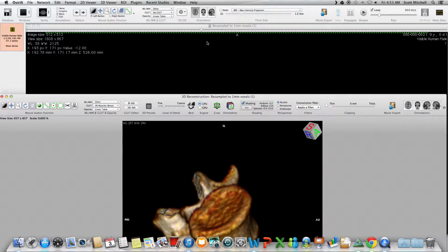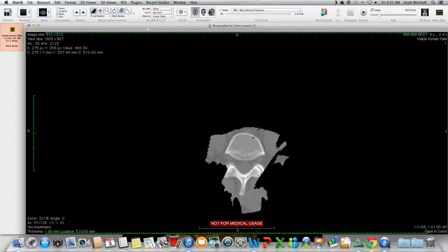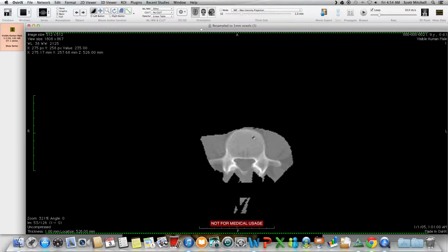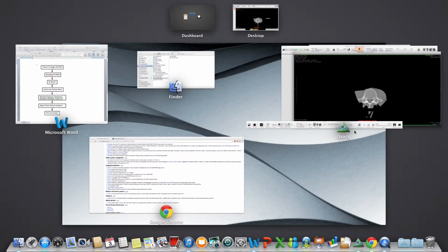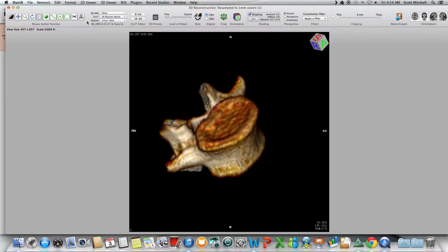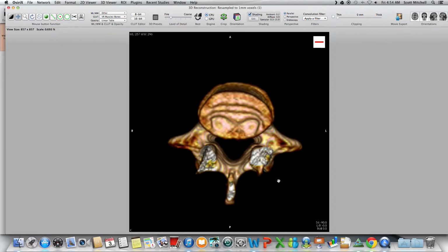So one thing we have to do is, if we go back here, we'll see, because of the 3D volume rendering, I'm just making sure I got that, okay. So 3D volume rendering applies windows to this, but our scissoring cut out all these little extras. So what I want to do is go back, oops, on the right one. So I've been mostly using the scissoring to delete, but what I'm going to do here is to ensure that the scissoring deletes everything outside of the lasso.